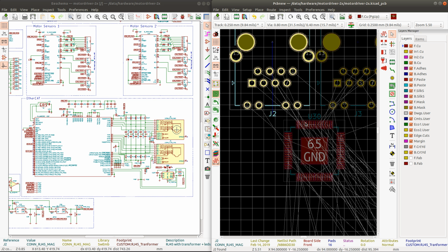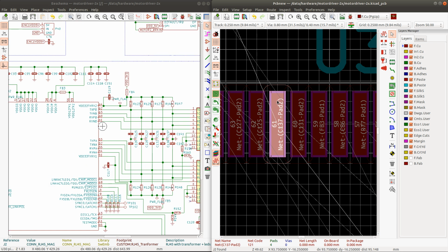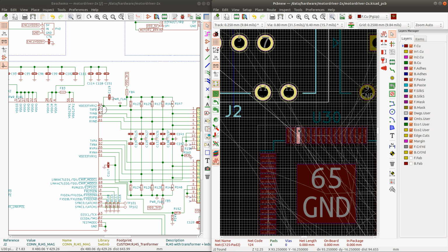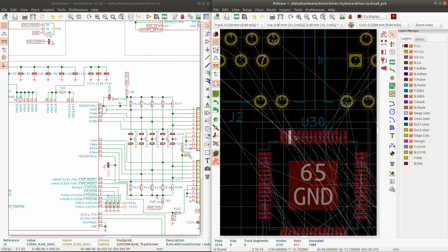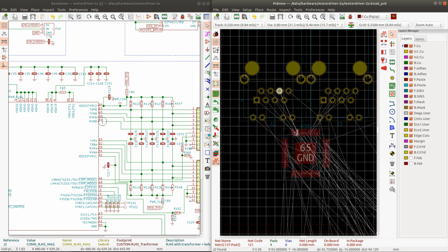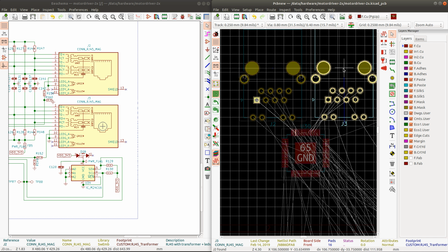So ideally this should go to the positive, because these would be differential pairs. Let's see, we have the RX pair there. So this shouldn't cross ideally. That one goes there and this one goes there. That's really weird. Is my connector wrong pinout or some non-standard pinout? Because it's the same thing with that one.